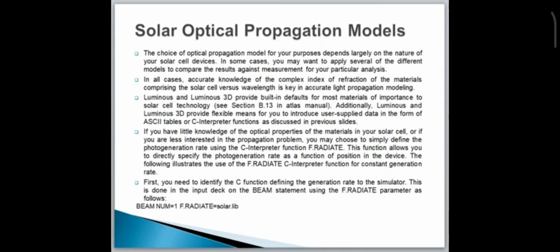If you don't know about the optical properties of the materials in the solar cell, or you are not interested in the complex propagation problem, it is better to choose the F.RADIATE statement in the beam for a constant generation rate.